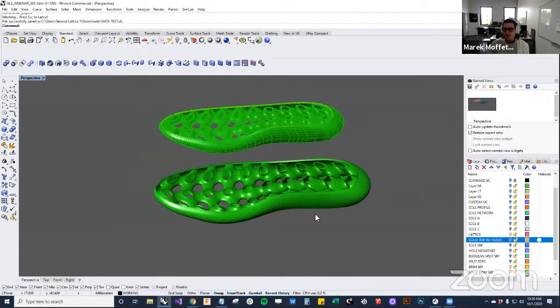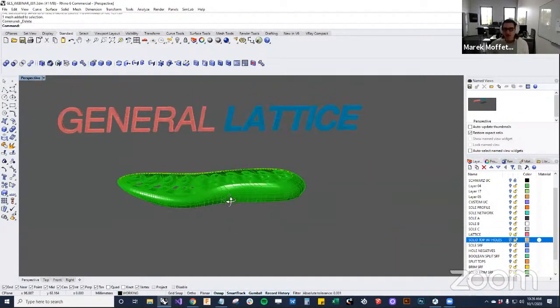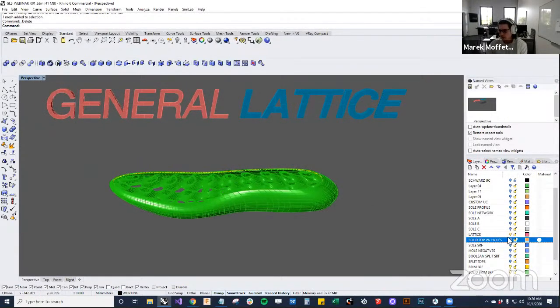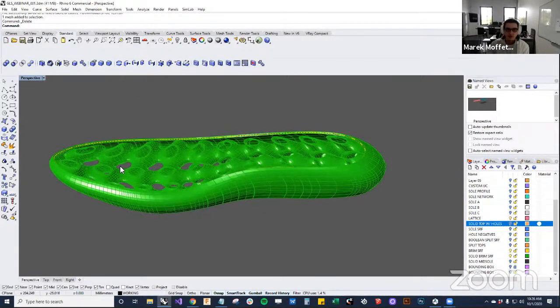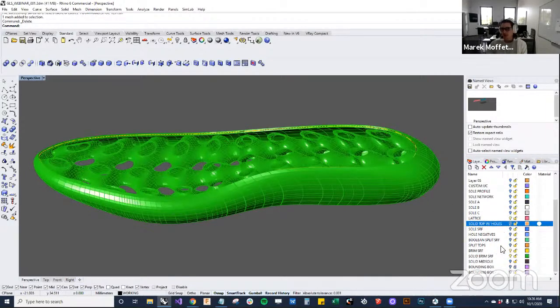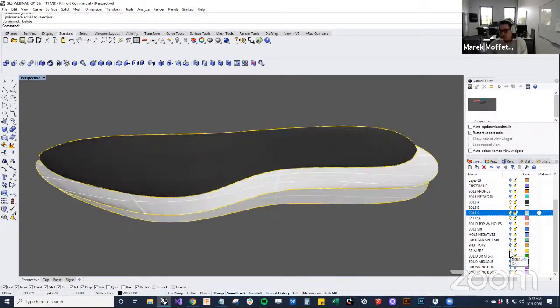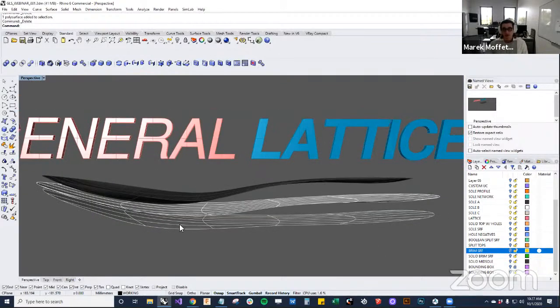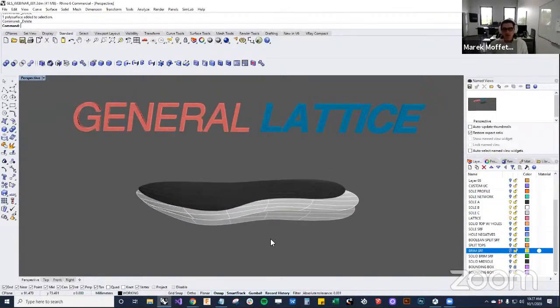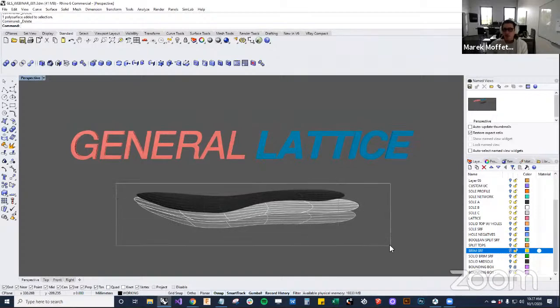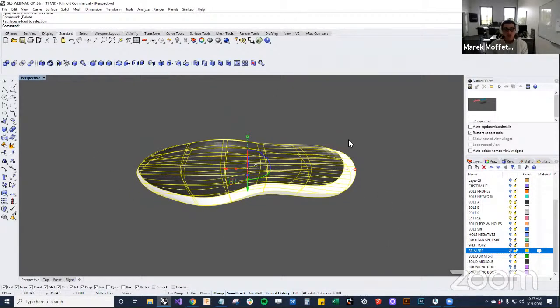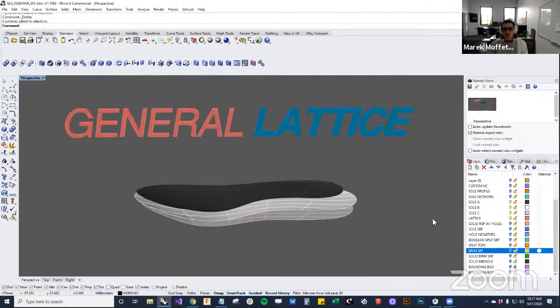So back to Rhino. I wanted to show one other technique that is sort of widely used in the community and can be crude, but can also be extremely useful. So similar to creating a lattice through three different surfaces, such as we see here, remove the brim. This technique is great and can be used for lots and lots of different applications. But another technique, as again, the community has seen quite a bit, is known as the Boolean intersection technique. And that would be the concept of throwing a bounding box around all of the geometry you want to lattice, and then subtracting that lattice.